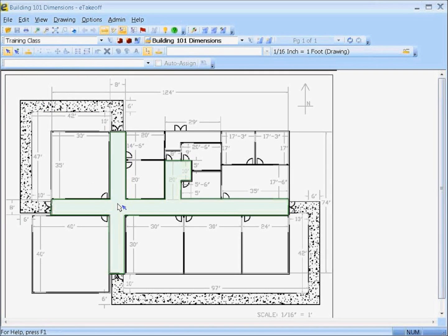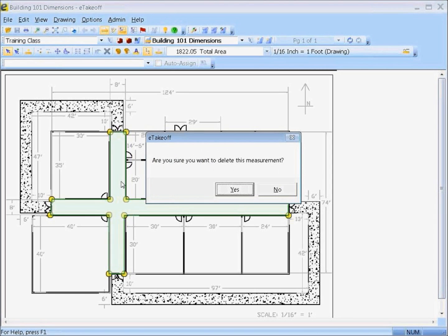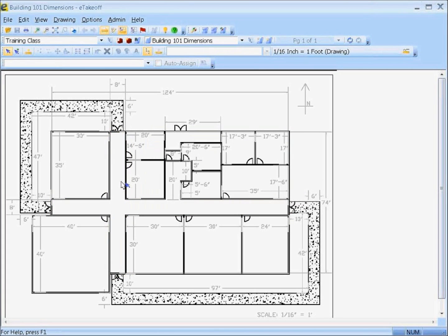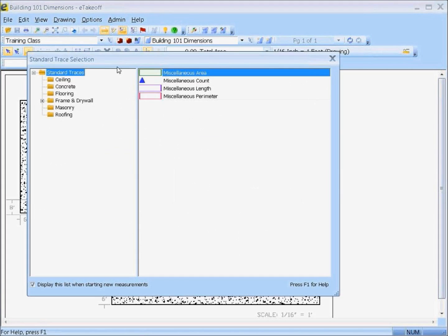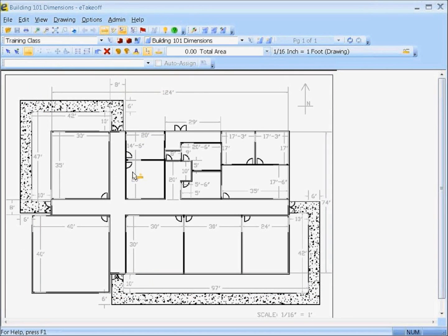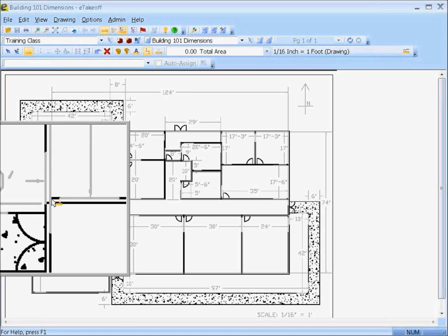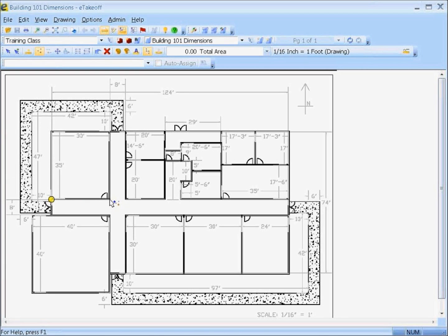If you can see this green area here, Nick just did a nice little 20 by 20 room. I'm going to get the carpet and cove base corners and so on for this hallway. So I'm going to delete that measurement real quick so we can measure it again. If we were measuring this with a ruler or a scale, we'd have to get it out, make a bunch of rectangles and add all that up, and I'd likely mess up the equation. So I'm going to click in here and just measure around the room. I won't be as slick as David because he's pretty awesome, and I won't be perfectly fast, but we could click and hold and get real close. I'm going to go kind of fast just so you can see it.